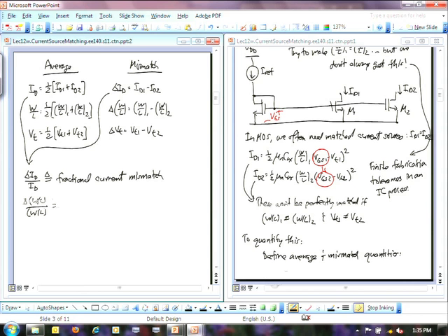And so I have that VOV squared. But when I factor out the W over L, I end up with 1/2 delta W over L divided by W over L minus a delta VT over my overdrive voltage.